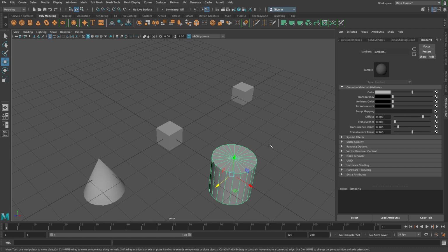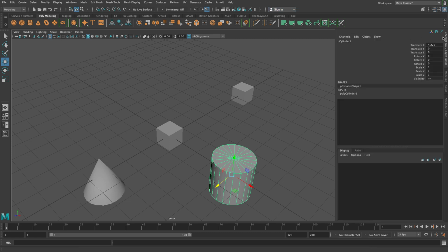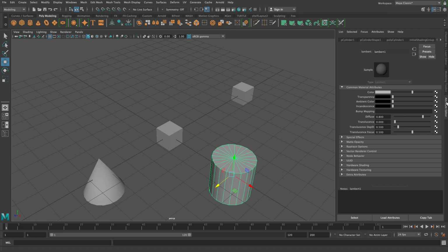These are all things that we're going to cover later on. The important thing to know right now, the takeaway, is that by using Control A, I can get into this thing called the channel box that allows me to put in custom coordinates for something I create, and the attribute editor, which tells me a little bit about that thing and all the different, how do I describe this? All the sort of different tools that I've utilized on the things that I've assigned to this mesh. So I hope that wasn't too convoluted.